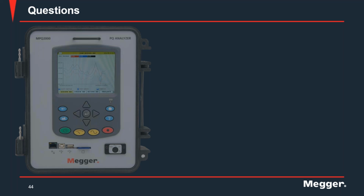Absolutely. Whenever you hook up a power quality analyzer, we want to make sure that we record all the necessary data. Typically with our units, when you select one of the default setups, you're going to be recording everything, so it's really not an issue. You can just start recording. When you do that, you're going to get all the harmonics, the interharmonics, all your swells, sags, transients, and rapid voltage changes. You'll also get total harmonic distortion and total demand distortion.